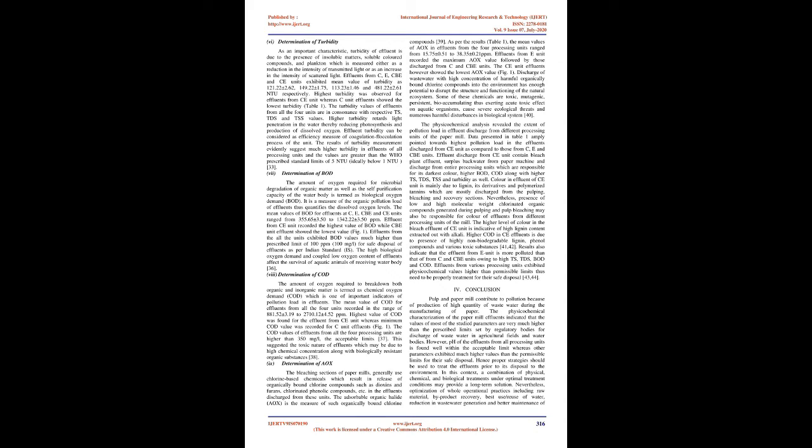2. Measurement of color. Color of effluents or wastewaters depends on the concentration of lignin, which comes from the presence of low and high molecular weight chlorinated organic compounds produced during different processing stages like pulping, bleaching, and alkali extraction as lignin degradation products. The color of the effluent from all the 4 processing stages, measured in PCU, showed considerable variation, ranging from 481.44 ± 0.58 to 3936.16 ± 5.76 PCU.